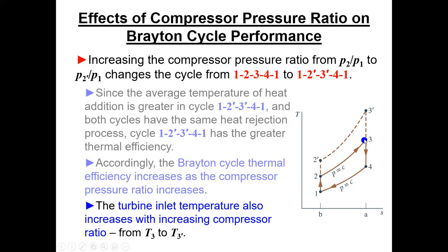Well, it depends on the metallurgy, what the blades and all that stuff's made out of. It could be. If they're already operating at 3 at the peak and you jerk it to 3 prime, well, we did it in the computer and it looked real good, but when we did it in the real world, it melted the turbine blades. Not so good. So that's always a consideration.